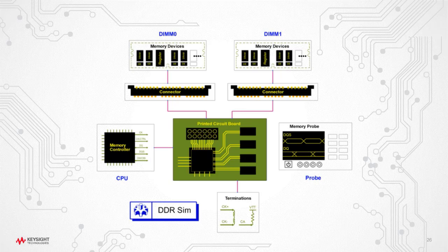Oh yeah, great. One thing that's important to note is that when you just look at the trace length in the layout, what you really want is to look at electrical length. Quite some years ago we had a good video where we explained the difference between switchback routing and serpentine routing, and you end up with two different electrical lengths.